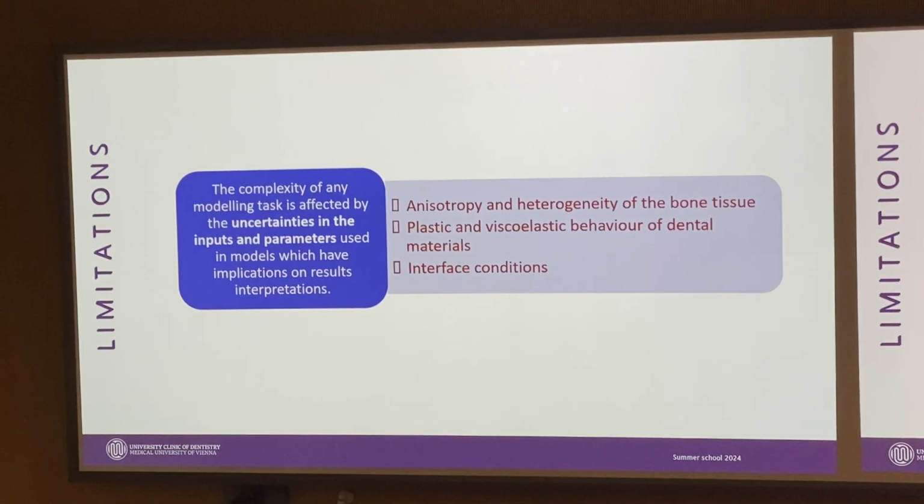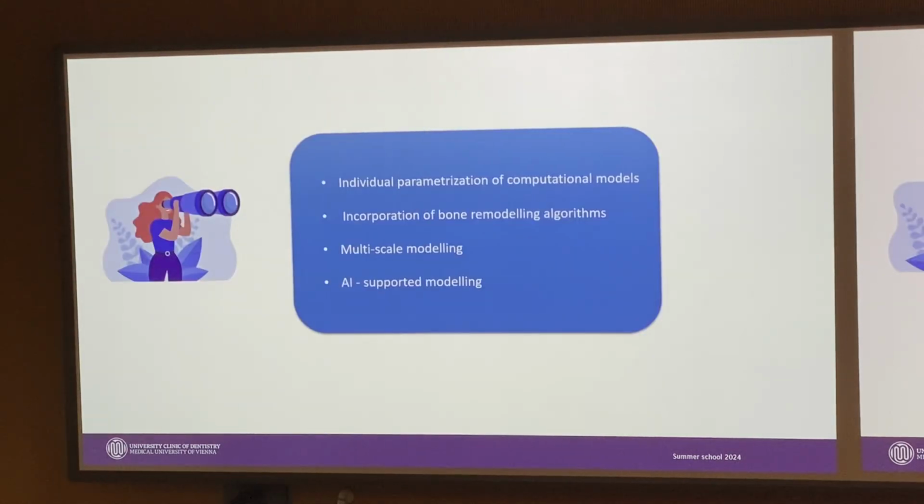Another consideration is the simulation of interface conditions, where the majority of in silico studies, including also our research, assume perfect integration and bonding without really accounting for the potential micro-motions at mating component interfaces, which obviously impact the loads. So addressing these limitations and improving the quality of simulations requires further research and development.